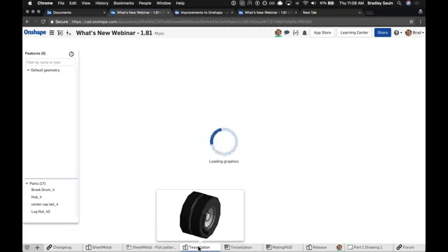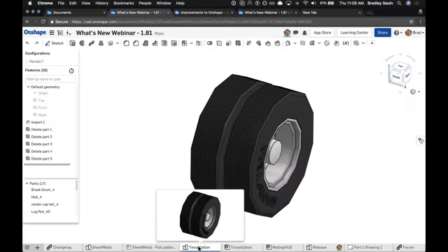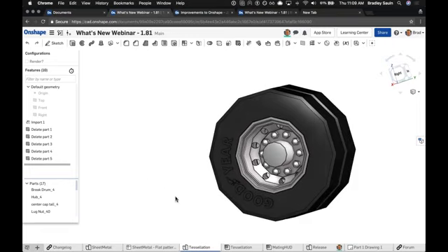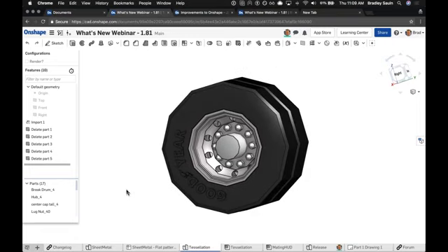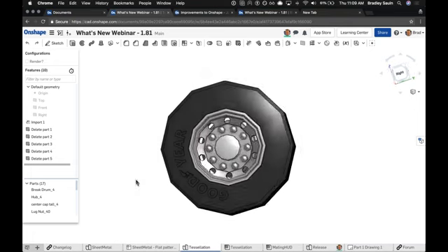and I have created a drastic example, but there are probably times when people have gone into Onshape to try to edit some specific detailed components or look at larger parts and not always see the best looking model. Based on performance, Onshape would always auto tessellate the model information. So you might end up seeing something blocky like this instead of a complete circle. Now, of course, this is just visual.